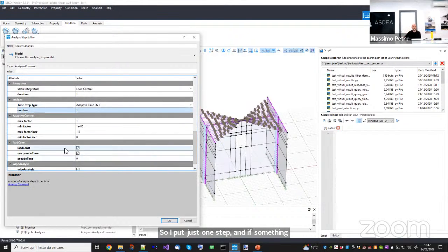After this, always remember to keep the load constant and reset the time step to 0 before you do a displacement controlled analysis. This is very important. So gravity loads will be kept constant at the current value, and then you can safely reset the pseudo time step to 0 for the next analysis.